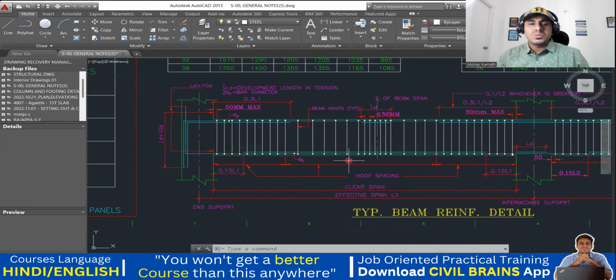Next comes the development length. So you know what development length is. Where does your development length start? If this is my column, from the face of the column, my development length will start. Right? This is the face of the column. From here, it will start. It will go all the way like this. This is my development length, which is mentioned here. LD plus 10 times the diameter is shown like this. Understood? This is called the development length.